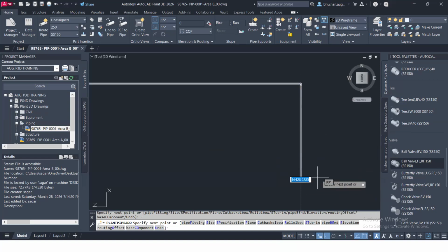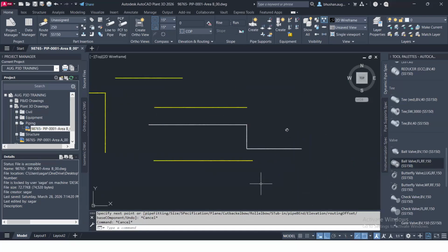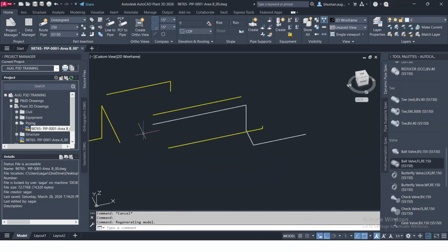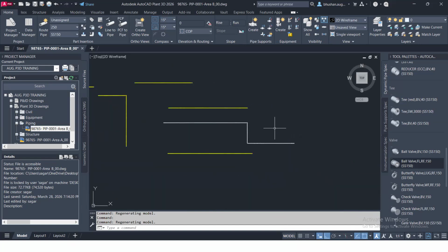If you have done 2D pipe routing, in that 2D pipe routing you are running the pipe, but it shows the pipe going above, with a 2D symbol, right? In 3D, you can route the pipe and also change the elevation by changing this plane option.